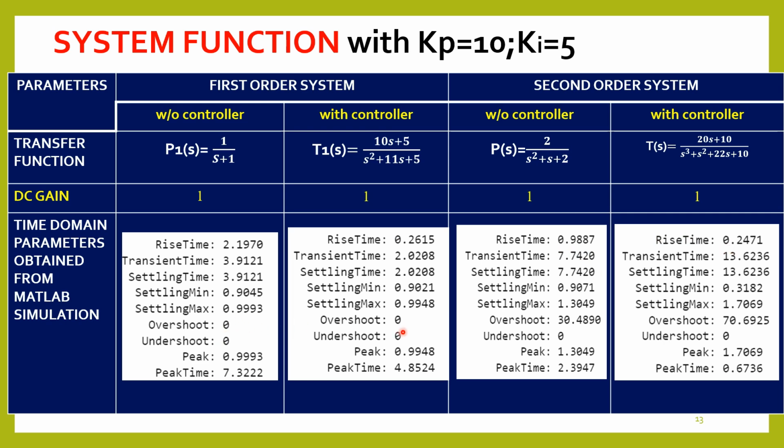My first order system will not provide more overshoot, but my second order system has increased overshoot because of the introduction of zeros. And my peak time has reduced with adding the PI controller. It means the added zero with the PI controller may adjust my transient response, and hence the speed of response is fast. It also makes the steady state error become 0.